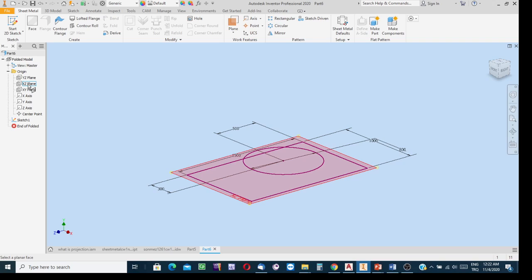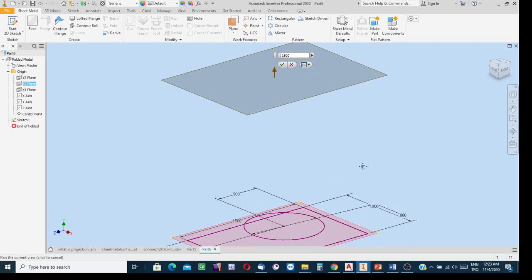Having the sketch plane, I had these sketches, so show this coordinate plane as the reference for this offset plane. Here at that stage, as the offset distance between this reference and this work plane, considering the total length of the loft between the inlet and exit cross section, the distance, let's say, is 1800 millimeters in the example, and then say OK.